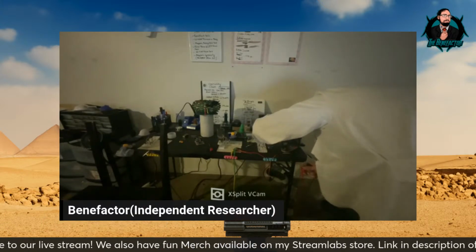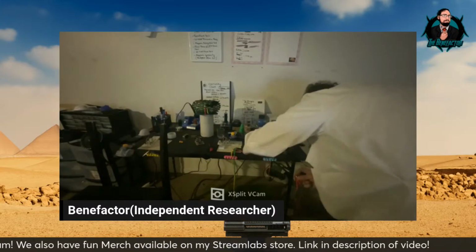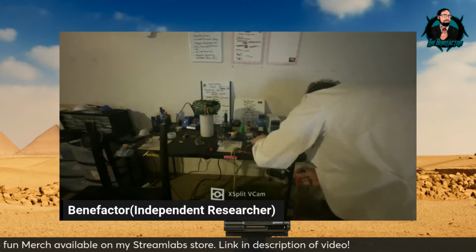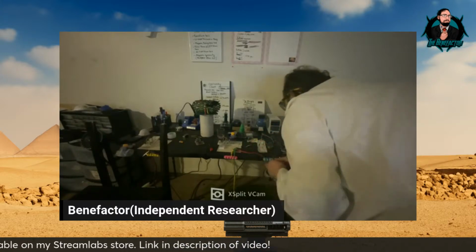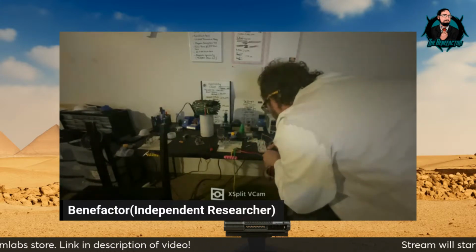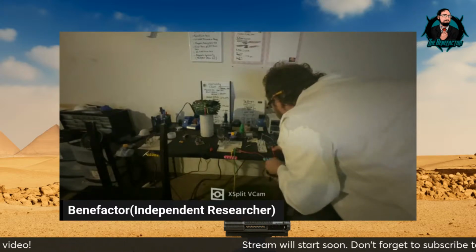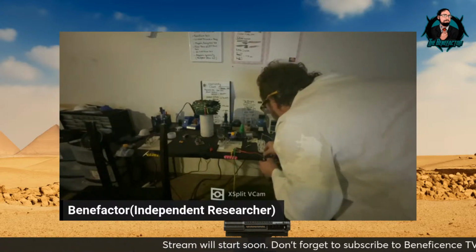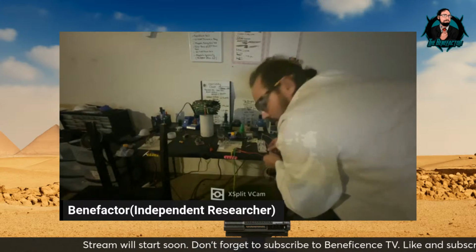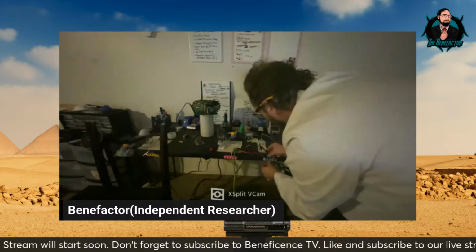Yeah, most people forget to measure that on their coils. I make it a point to never forget that now, because it tells me how many volts you need to give it to get any kind of current through it. That's the threshold right there. That's important for sure.